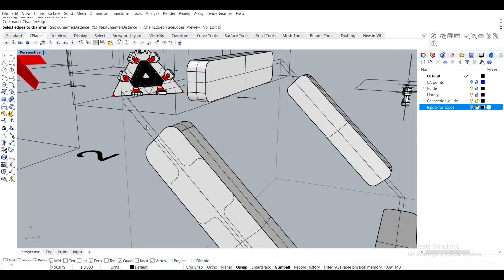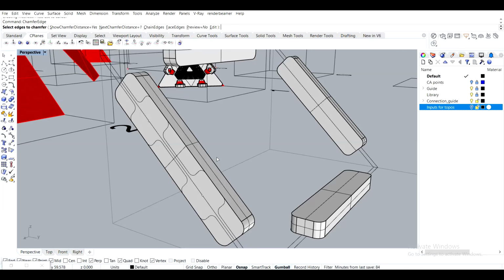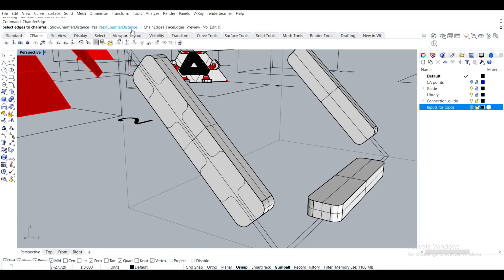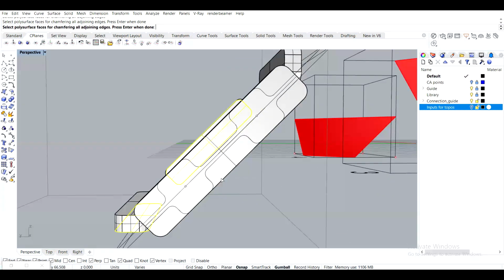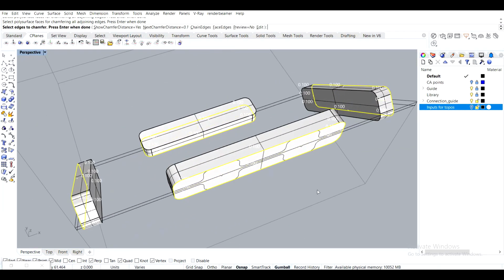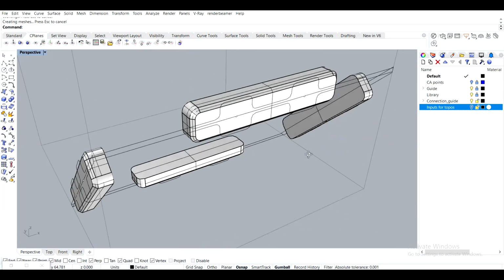In this case, I won't use fillet, but rather chamfer, just because it's less heavy, and I want it to be less heavy. So next chamfer distance 0.1. Let's try that. Oops. 0.1, and face edges. I'll be using face edges rather than just regular edge selection, because it's going to be much faster. Okay, we have something like that going on.